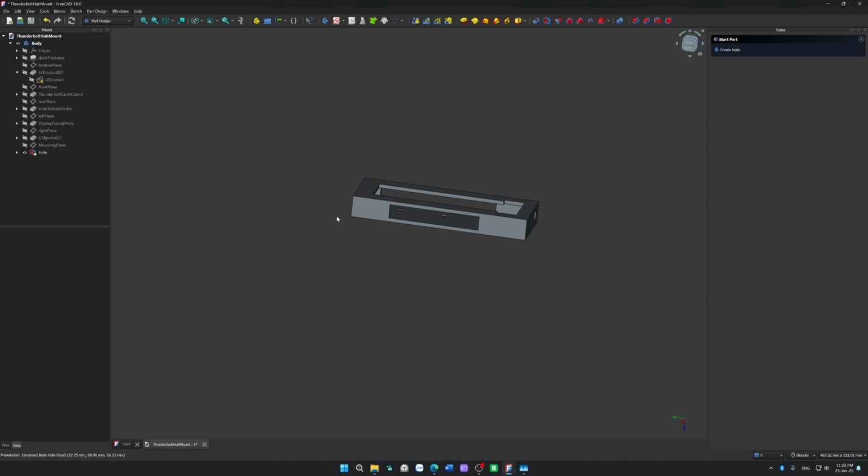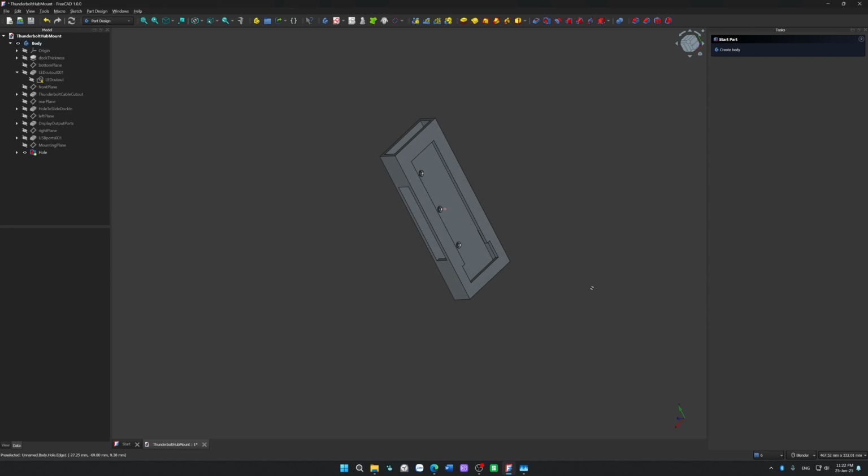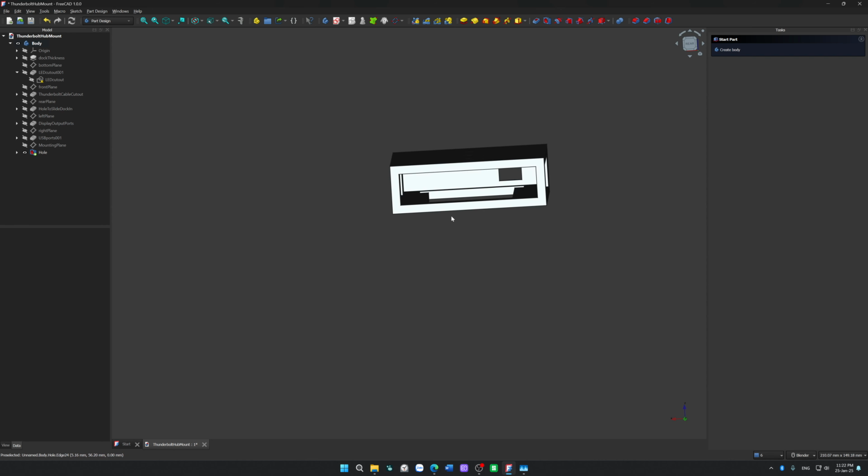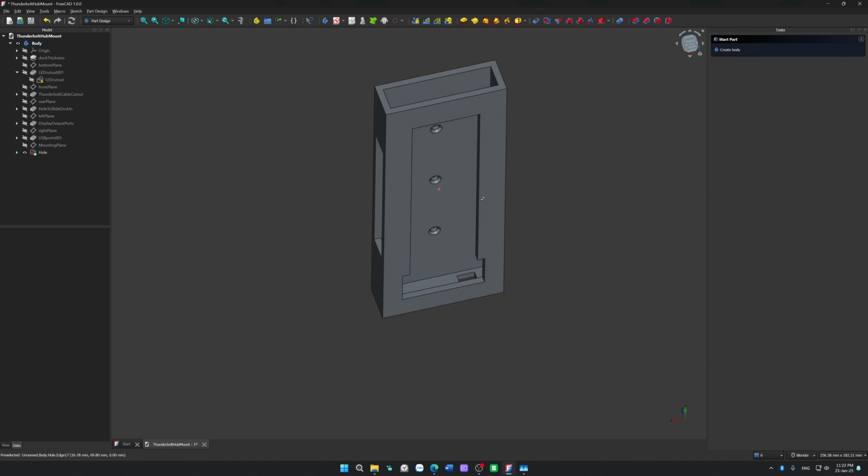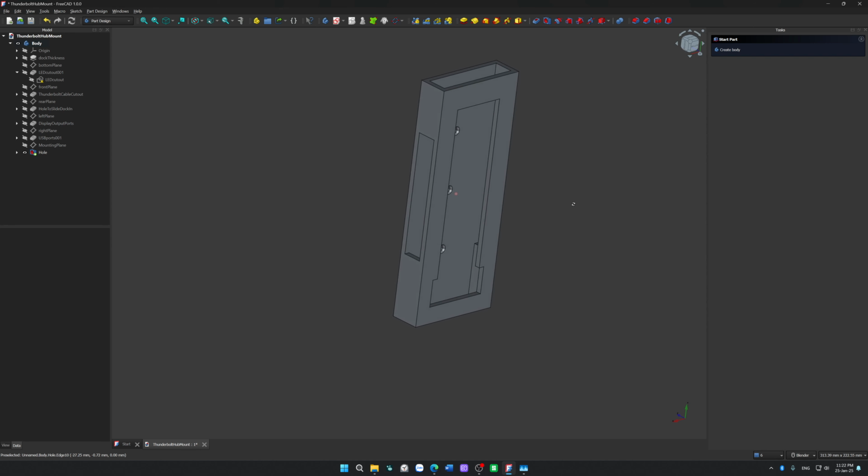It might break off right here due to the snagging, but if it's printing this way, it will have to flex through the strongest part, the strength of the material itself. Yeah. Let's add some chamfer.